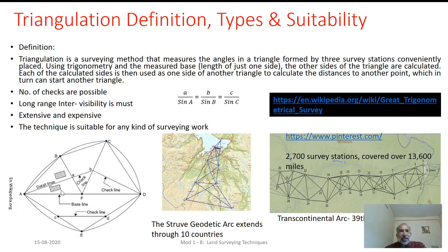So here, AB as well as BF is determined by making use of the baseline and all included angles. Having BF with us, as we measure angle B, angle F, angle C, subsequently we will be able to compute all the sides of the triangle by making use of the sine rule, and accordingly we can proceed further.